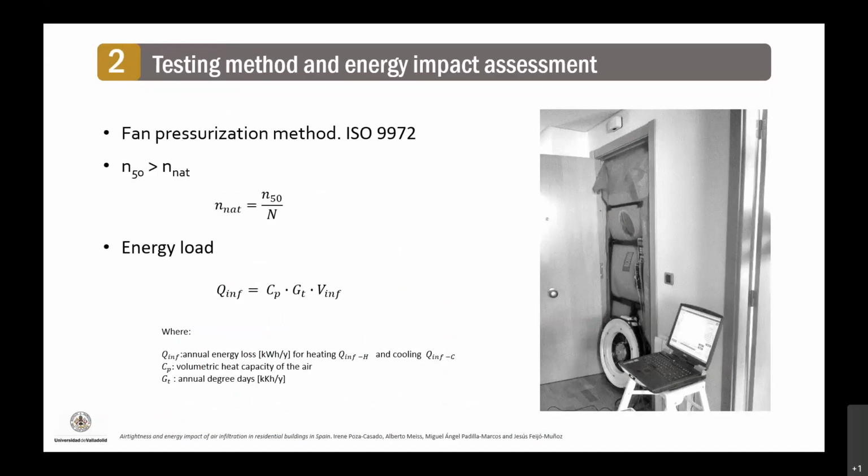Afterwards, the relationship between the air change rate at 50 pascals and under natural conditions was assessed. A linear relationship was considered by means of a correction factor N scaled according to climate, air leakage path size, dwelling height, and shielding, being aware that this is a simplified treatment of a complex reality.